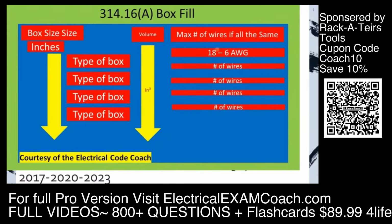Then when we come over here to the far right of the table, it's one of my favorite pieces. It's actually like a cheat sheet. If all of your wires are of the same size, you can use this part of the table and make it very simple on yourself. First thing you'll do is you'll come over and find your gauge of wire. Then you'll come over here and find your type of box, and then come over and tee off with how many wires can fit inside of that box. It's very simple. Now let's look at the second table that we're going to be dealing with for box fill.